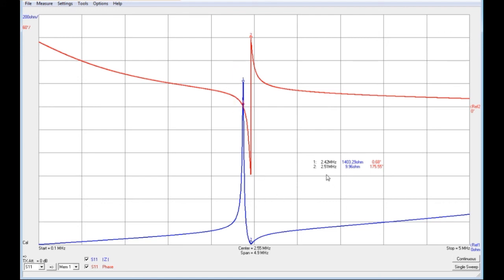2.42 megahertz. And a simple way of tuning that, as shown many times before, is to put a parallel variable capacitor on the primary, which tunes the primary, and then you can very fine-tune this system with those peaks moving around.